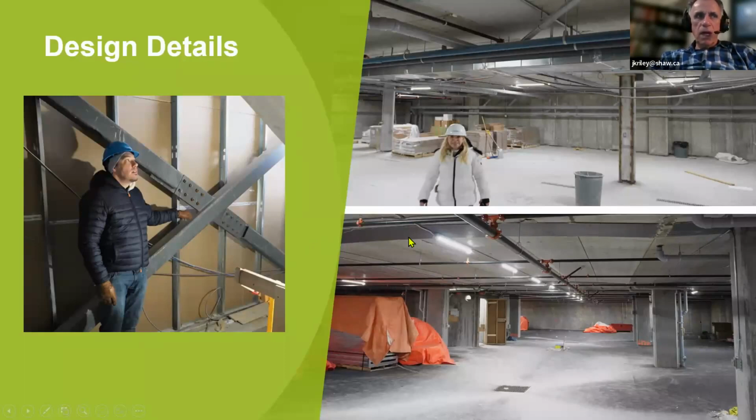Slope to drain. Because every other parkade in Victoria has to have slope to drain, and that water drains to the center because you have slope from the edges to get your 2% grade. Instead of doing it like that, we put a trench drain in along this line right here, and we take one of the hollow core sections out, and that becomes the trench drain. So we're using far less concrete, and the excavation into the ground is far less. You notice there's no beams. So we're saving 2 feet of excavation per floor when you do that kind of a situation.